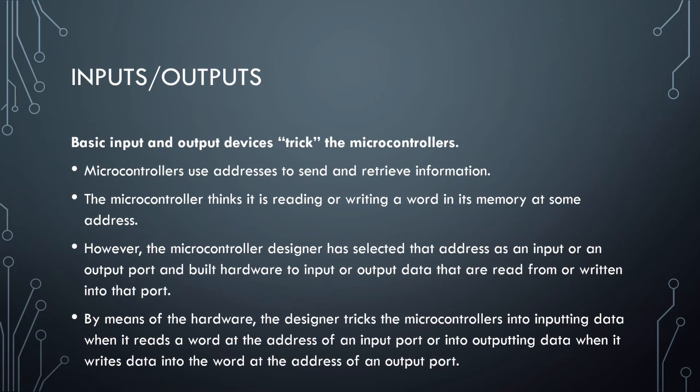Everything that's built into your board helps translate those signals into things that our inputs and outputs can read. So when we say digital write high to turn a pin on, things happen in the hardware of our board to turn that memory location, that address it's depositing information into, into an actual signal that then goes to our LED to turn it on.